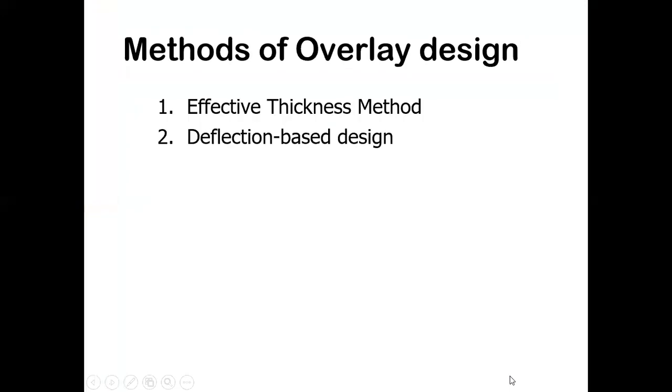So if you want to design an asphalt overlay, there are two methods. One is the effective thickness method. The other is a deflection-based design. In the effective thickness method, we do not estimate the thickness.